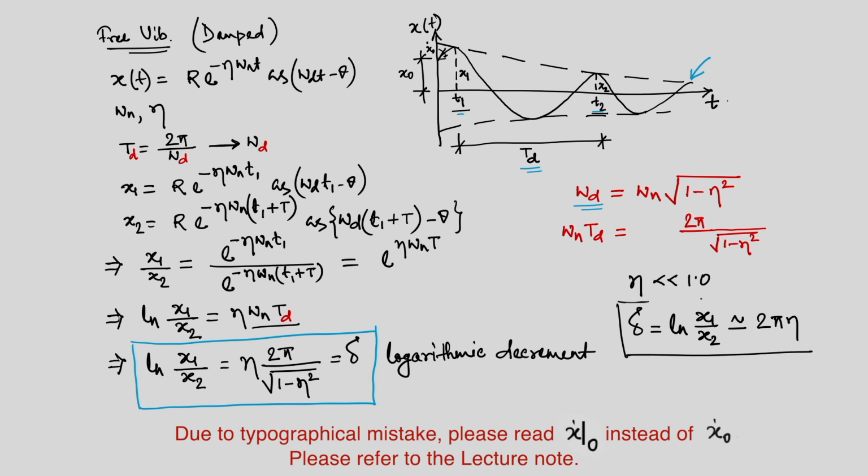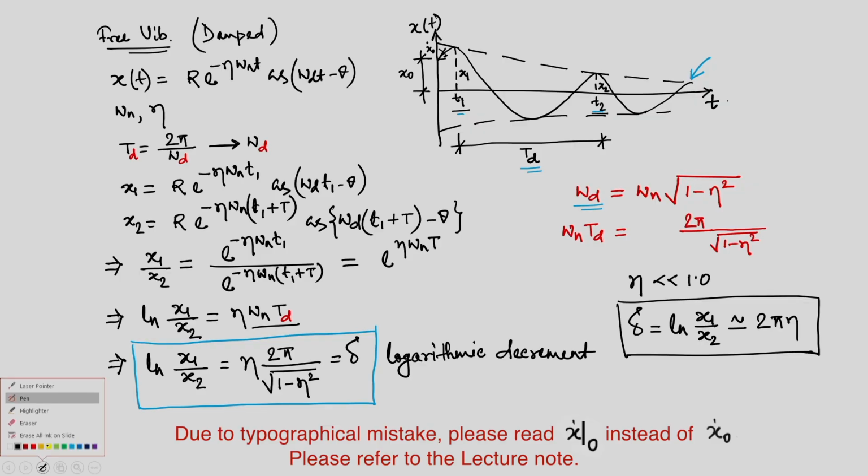So, that is the relation we have, and the technique thus is called logarithmic decrement technique. In this technique, what do we do? We measure the free vibration response of a SDOF system, which is having damping, and from the plot we can find out the damped natural frequency. This is the measured response.